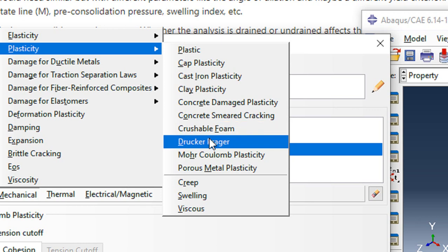All that depends on the physical phenomena that you want to incorporate in your flexible pavement analysis for the layers beneath the asphalt concrete. So maybe you would like to include consolidation and critical state concepts in your simulation, which will need these parameters to be decided based on the materials, right?